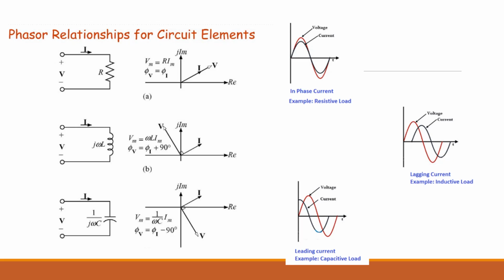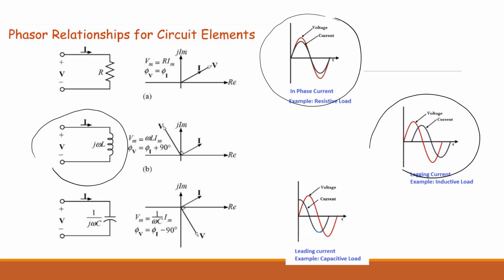Okay, so here when you consider resistors, I told you before as well, the current and the voltage don't have any phase difference. But if you consider the inductors, you can see you have a positive 90, so you get a j. So it is omega L j. j means 90 degrees. So it is always with 90 degrees, isn't it? Am I right? And this one is negative j. So it is a negative 90.